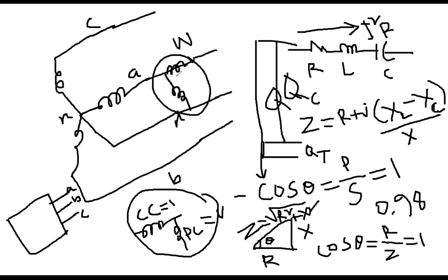And you have one wattmeter, single phase. So you see here I connected the potential coil, that means the voltage coil, one end is here, but the other end with the neutral. The current coil is fine, it is in series. So you can connect the current coil here, but where would you connect this potential coil, because this is B phase, this is not the neutral. So that's why it is not always possible that you can connect a single wattmeter through the neutral and you will get the value, and straightforwardly multiply by 3. It is not always possible. That is the meaning of that one.